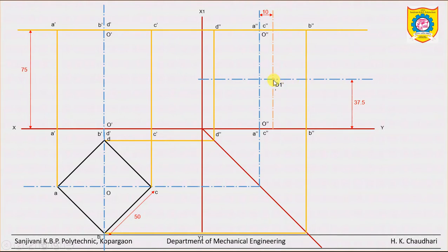So considering this point as the center of the axis, that means where the diagonals intersect, draw there a square left face. It is the matching face with the right square also. Okay, the size was 30 mm. So label the corners, or you can say the edges, in the side view as 1 double dash, 2 double dash, 3 double dash and 4 double dash.